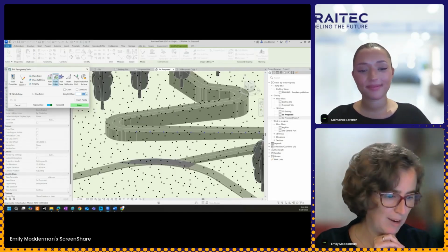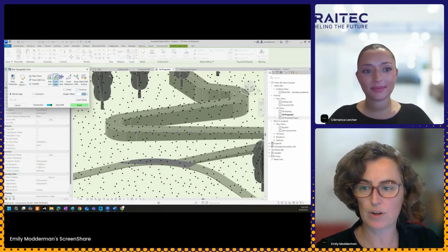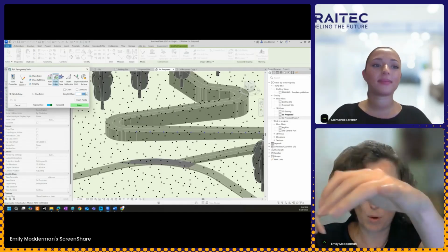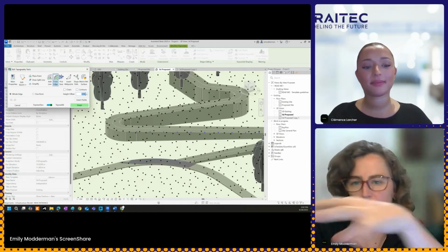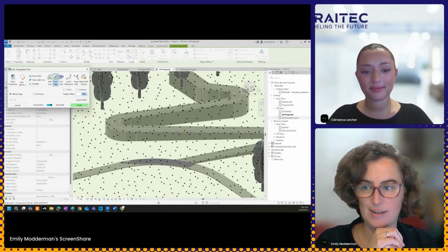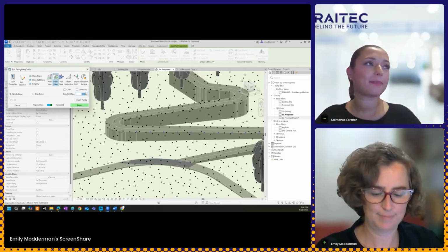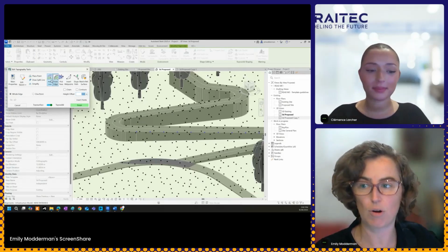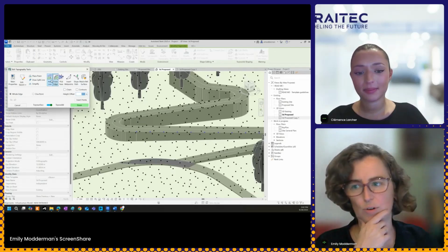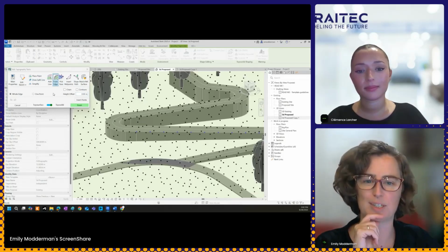And thanks for coming back with that information. So that's going to be your from edge or your pick face with some sort of height offset tool. At least that's what I would try first. It will keep any existing points and then increase and fill in any lost points. So hopefully that helps you out there. If you need to manually have those contours, you could draw specific line work at specific heights and use those to add to your topo. So you're in the topography tools for that answer. You've got a few options there.